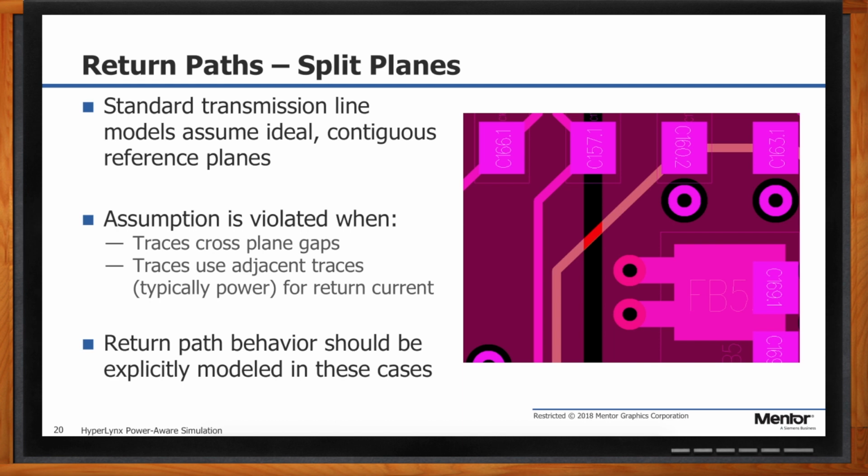So what we need to do is we need to have a reliable mechanism for figuring out if we have a trace going over a plane split, how do we effectively decouple those 2 planes, like with a capacitor, and quantitatively determine what the degradation of the signal is so that we know that, in fact, this design will actually work. So, we can't idealize it, or more importantly, we can't make it perfect by avoiding the split. We can't idealize it and pretend it's not there, but it's also fairly difficult to model it accurately and predict it. So how do we get there?